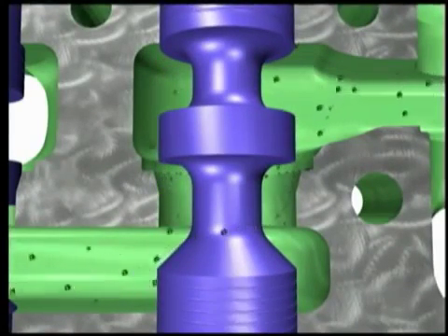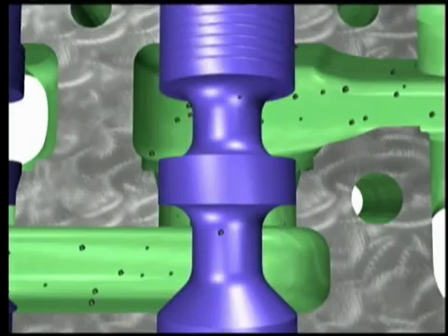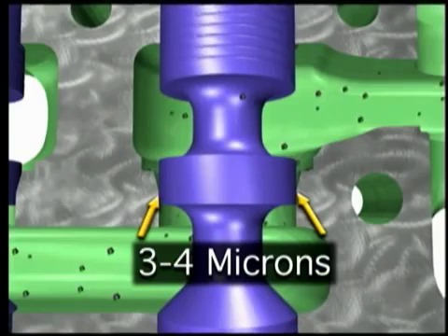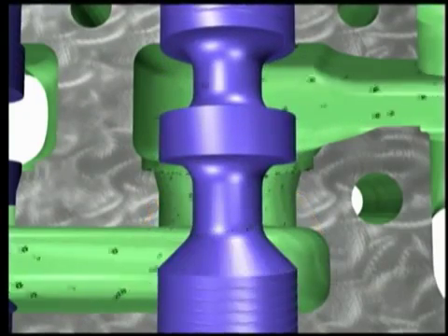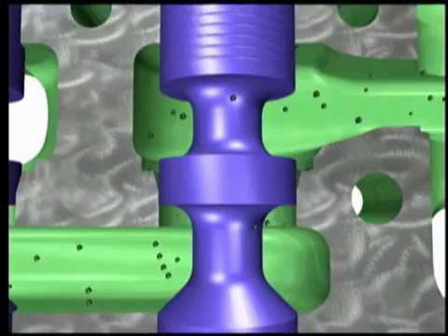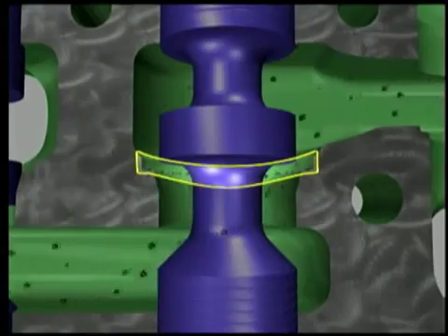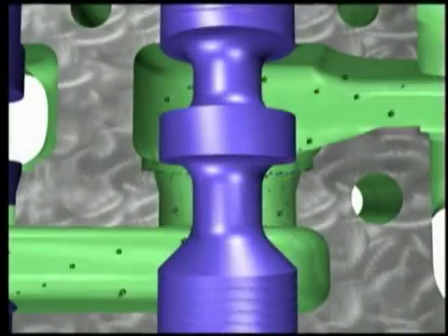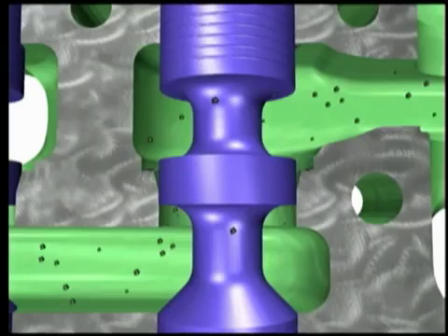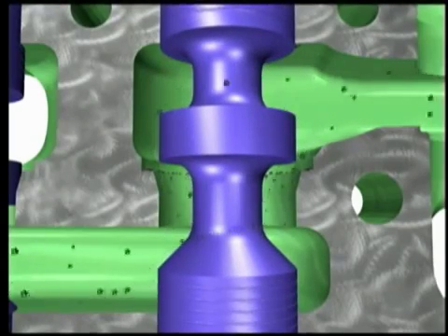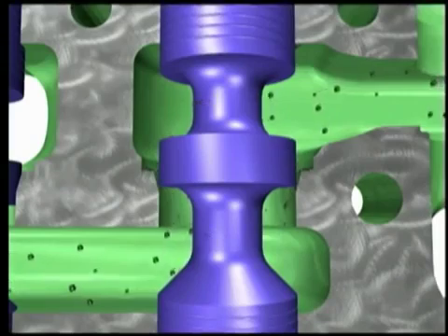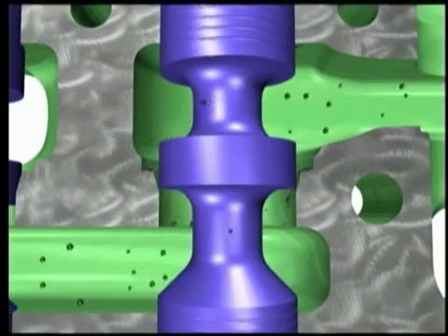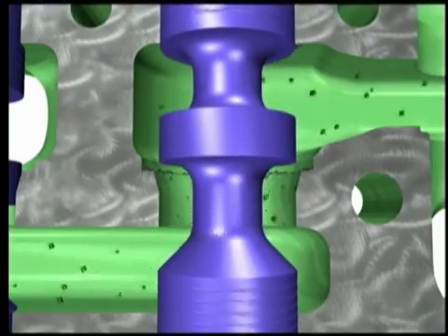Electro-hydraulic valves are more susceptible to contaminant damage because the clearances are even smaller, as small as 3 to 4 microns. Some of the particles naturally adhere to the imperfections in the wall, or because of the electromagnetic conditions in the valve. This buildup or siltation can either slow the spool, causing sluggishness, or make the spool hesitate, causing jerkiness in the system. Over time, the contaminants can cause wear on the spool that results in leakage. And sometimes a large particle can become lodged and block the motion in the valve.